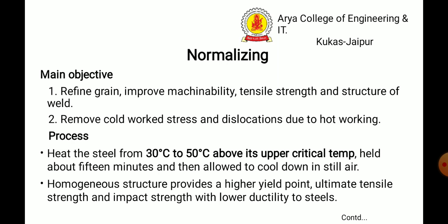By this normalizing we can improve machinability, tensile strength and structure of welds, and also remove the cold work stresses and dislocations due to hot working.